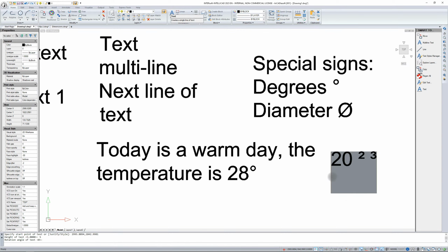If you would like to enter a tolerance mark, that is plus minus, then backslash U plus, and you would enter 00B1. And almost equal would be the backslash U plus 2248. And unequal would be backslash U plus 2260.